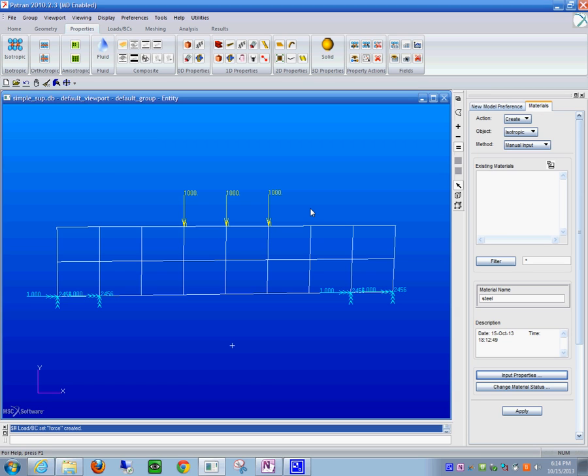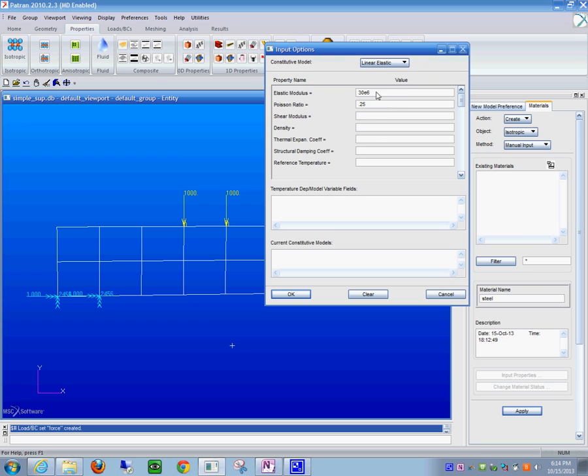If it's made of a composite, then we have different modulus of elasticity, and therefore we would need to enter specifications for both materials. In this case, it's an isotropic material, as we are defining it here. We put the input parameters, modulus of elasticity, Poisson ratio. We could do damping and so on, but we don't have information on this problem to do it.